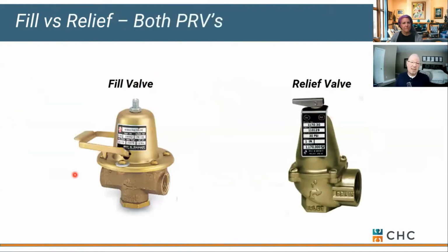You could see this in a residence that has hydronics in it. You could also see it in a light commercial building. If your building gets too tall, you may work outside the range of a standard fill valve, and if that's the case, you might need a mechanical boost, like a pressure booster, to get water to the top floor, okay?